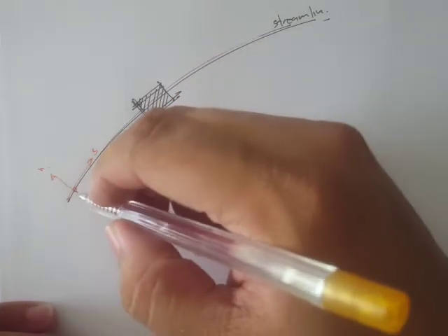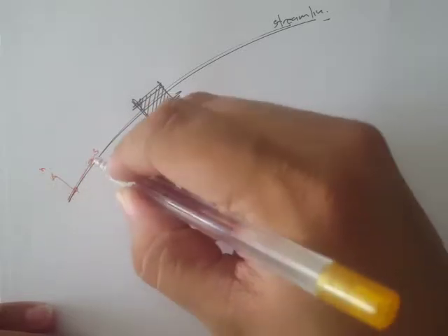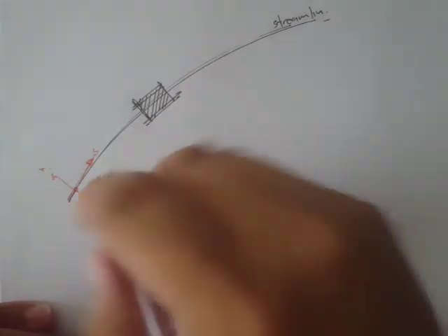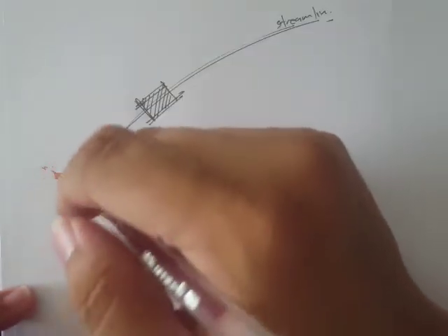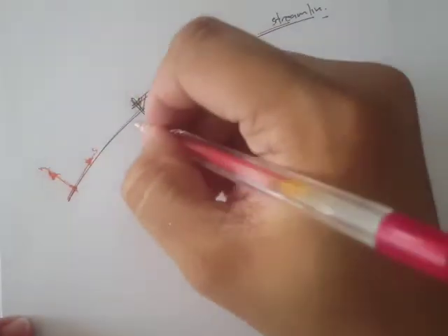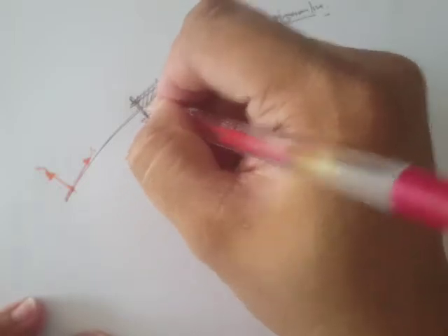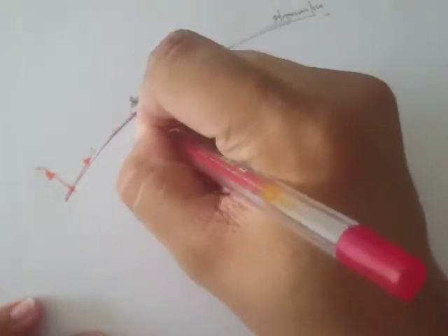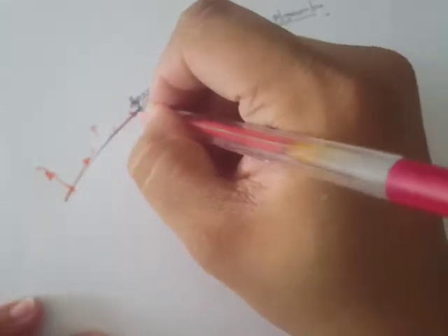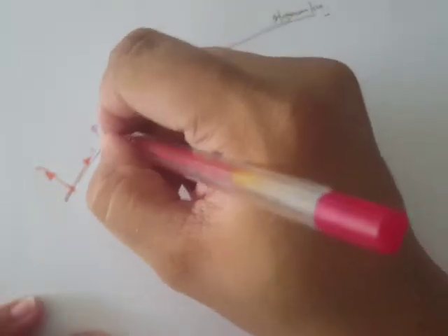So for the path coordinate systems, we have an axis along the streamline. So that's always along the streamline. And then we have another axis that's normal to the streamline. Okay, so let's now expose the forces. We have this force, a pressure force. Let's say this is P, the pressure P times the area to which it is acting.